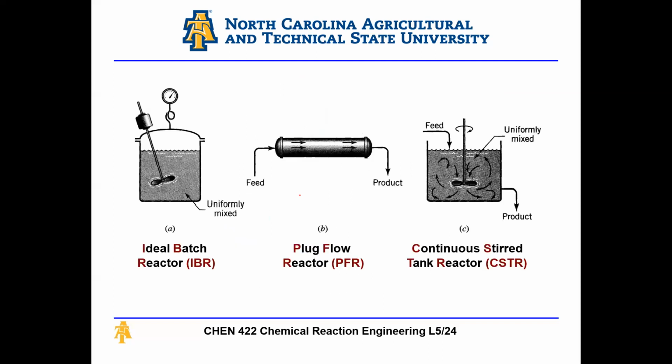Okay, then we move on to week number 3, where we introduced the 3 types of reactors. We said you have an ideal batch reactor, plug flow reactor, and continuously stirred tank reactor, and they're all very different. Batch reactor: I load chemicals into a vessel, I mix it, leave it, and then after some time I just take the product out. And this is non-continuous. Here I assume it's perfectly mixed. So a couple of things to know: this is not continuous. There is no continuous flow.